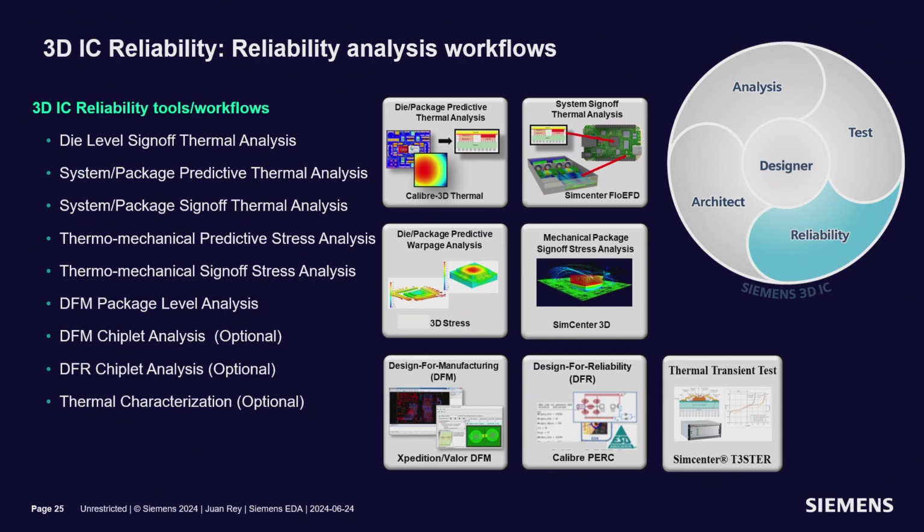That analysis also needs to be extended towards stress analysis. While mechanical engineers care a lot more about the lamination issues and warpage issues, which are absolutely important to make sure the integrity of the whole system gets proven, where the connections come into the EDA flow is that, both for thermal and for stress, you may need, in many cases, to understand the connection that exists between either thermal or stress and the actual device characteristics.